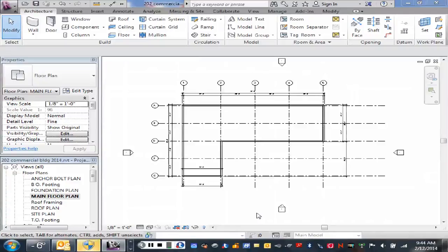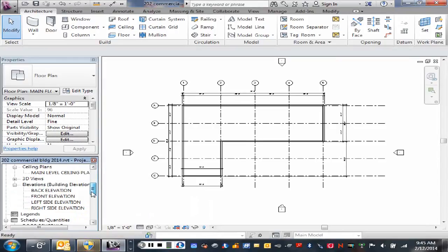We're going to talk today about creating your height elevations on your building. We talked about the building being modular, so it's masonry construction, so we have to be modular on an 8-inch increment horizontally, right? And we have to be on an 8-inch module going vertically as well. So let's just look at maybe an elevation of our building.